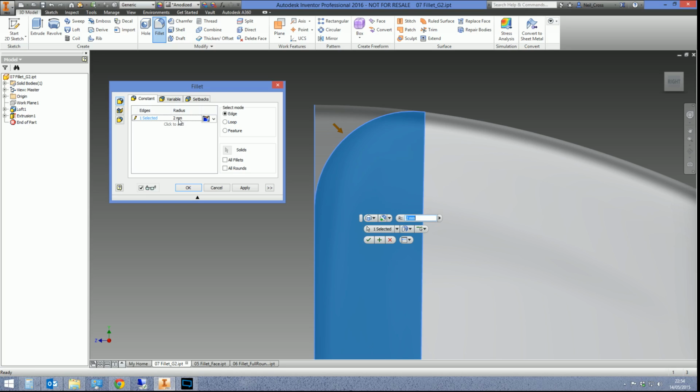And it'll be a 2 mil radius circle. So that's what a tangent is. If you change this to a G2 fillet, it changes very well. Actually, that's quite a dramatic one. This one is no longer a circle. The fillet is actually exiting the edge in a spline fashion.